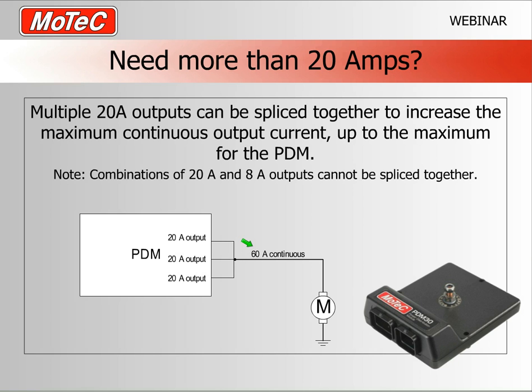And now this is a good example of where we use our global conditions to control an output. For each of these outputs, there would be no point in setting up an individual logic equation, if you like, because I can set it up as a global condition, and then each of these outputs just simply refers to that global condition. So it's a much faster way to set the thing up.